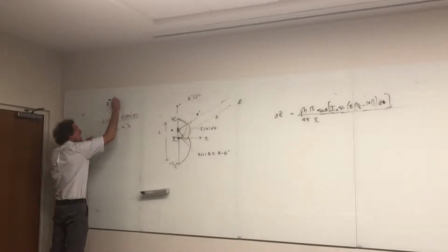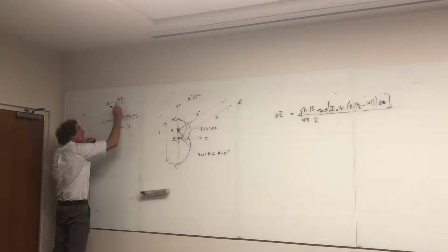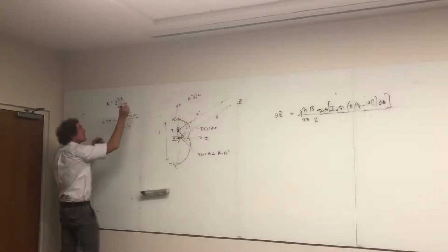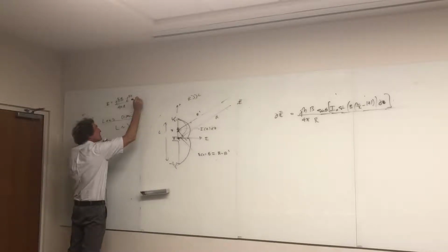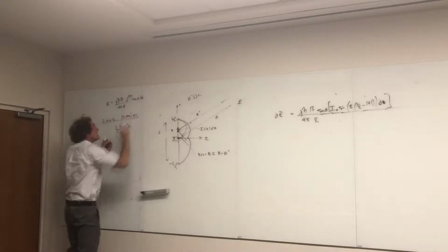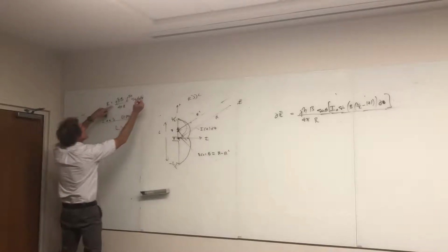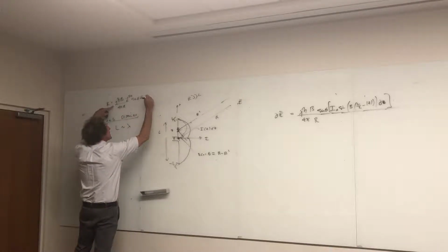In case you're not following me, remember for a short dipole, in general, the E field is given as j eta beta over 4 pi r. This one you have to know. Then it's times e to the minus j beta r times the sine of theta a theta. And something I didn't put in here is the I naught times L.